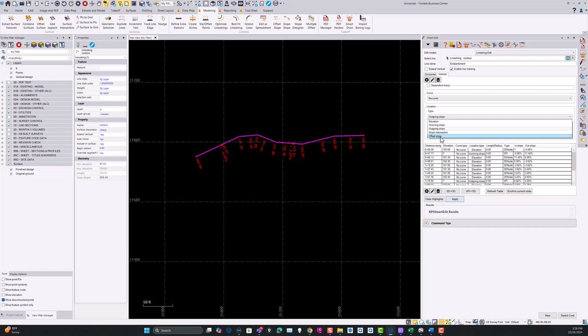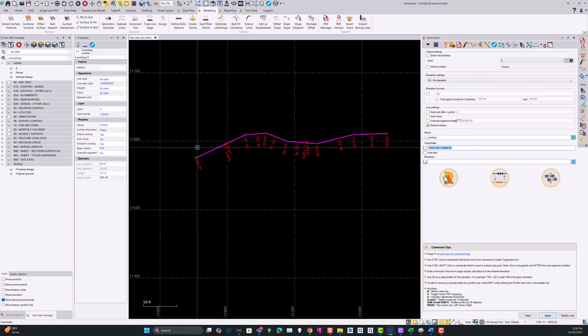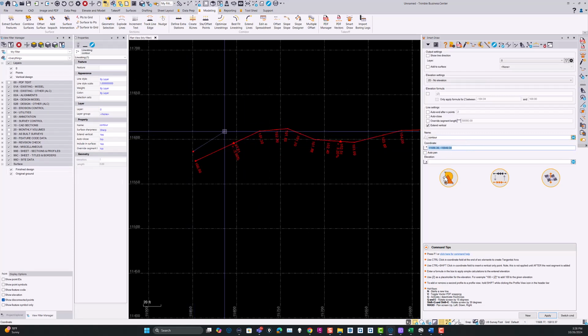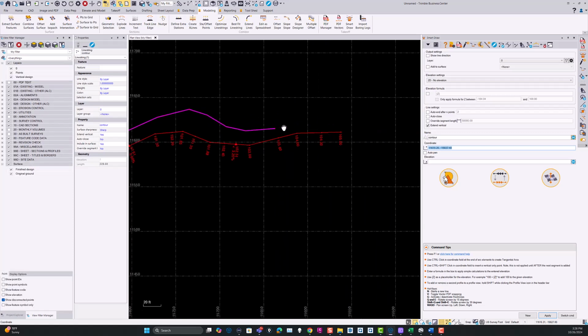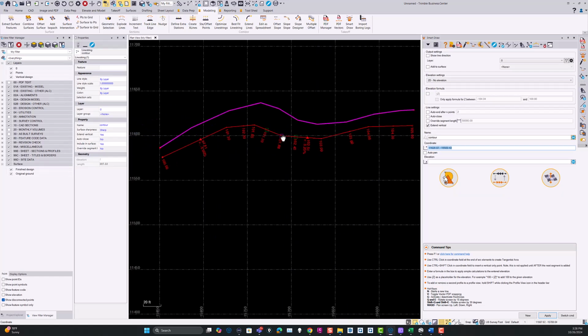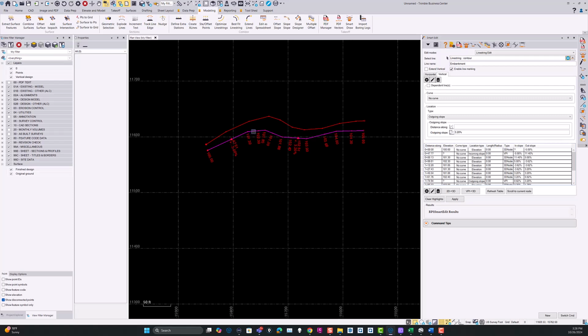Now the other thing you can do is this offset slope, and before I do that, I'm just going to switch command and go back here to the Smart Draw command, and I'm going to draw a 2D line here just to show this. And the 2D line, I'm just going to draw a line kind of running along here, but maybe variable height. And just imagine we've got the top of embankment slope that we've just elevated, and now we've been given this 2D line in the plans, and we know that that line is at a 3-to-1 slope from the reference line, from this line.